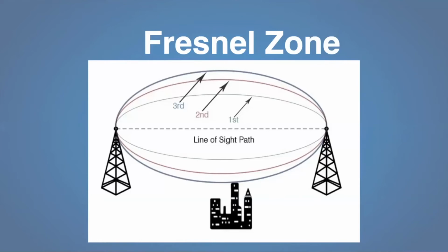So there's one other thing that kind of went by quickly on Jason's calculator that you may have a question about. There's a thing called a Fresnel zone. This is the way that your power spreads out from your transmitter. It blooms out into this Fresnel zone. You can add this in. Actually, Jason's calculator is going to show you what this is for your specific system. So it's handy when you look around at your antenna placement. That's really what we're getting back to with this. So you'll see there's a first, second, and third Fresnel zone.